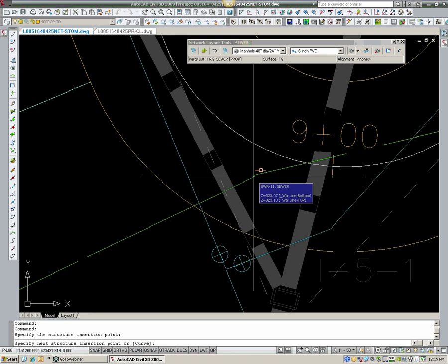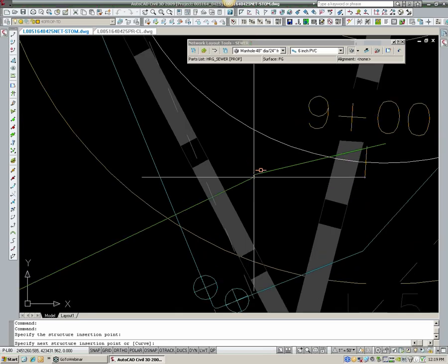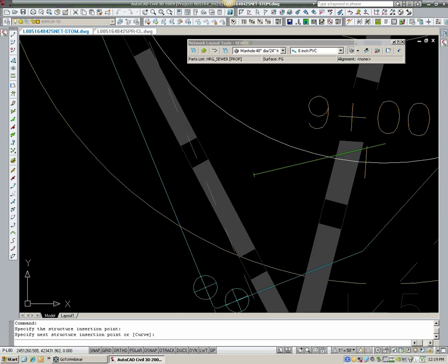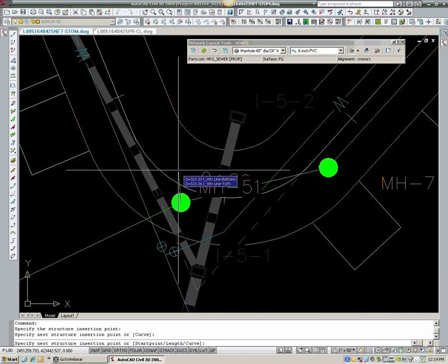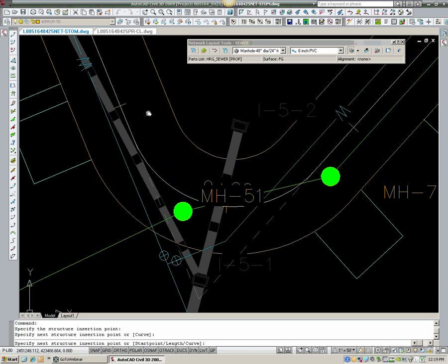it's a closed, sort of like a square with two ends coming out on either side. Wait for that glyph to come up and then pick, and that will place a manhole and connect both pipes to it. So that's if you're connecting into the end of another pipe segment. You see the glyph's a little different there.